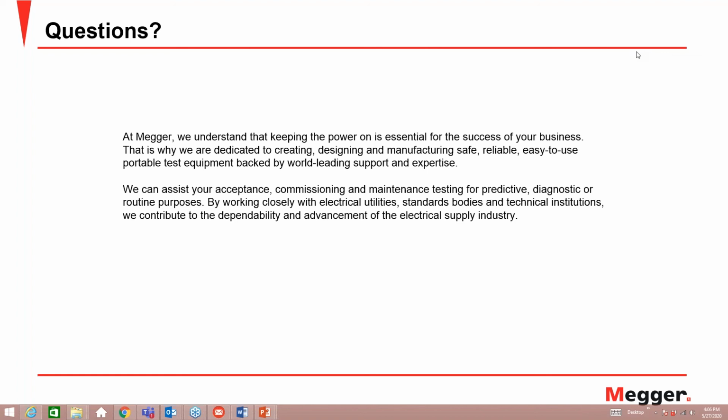As long as the BMS is operating, if you're concerned about safety, make sure you get a chemistry that has a higher temperature ignition point, because it'll be much less likely to go into that catastrophic failure mode. Now, also keep in mind, this is a new and evolving technology, so there is no real set maintenance on this.